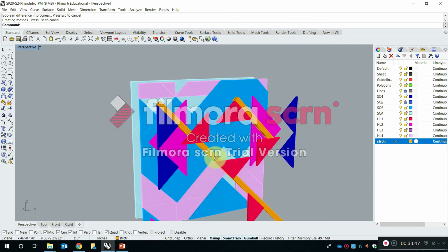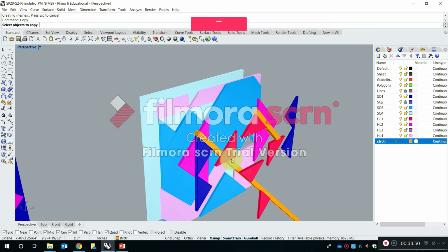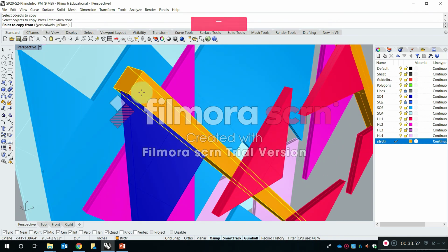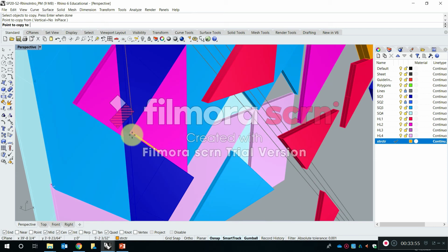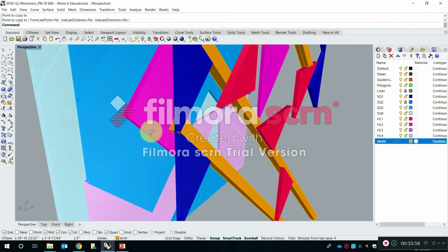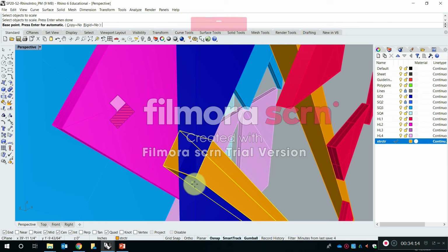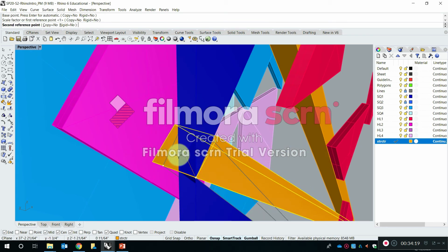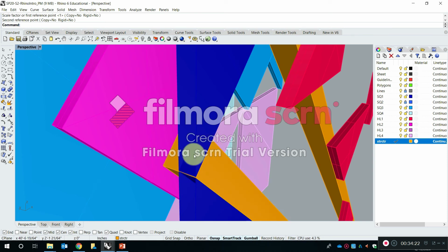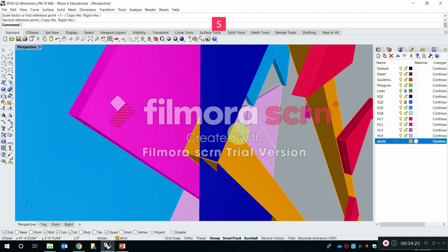All right, and let's say that once you have one of these basswood sticks, you had 1/8 inch sticks because that's what you found. But now you're planning and doing this project again. It's like, man, I really like how Javier had this basswood stick that was 1/16. Much cleaner. So I can do a scale now of two directions. Select the basswood stick, from there to there and to there. Hey, what happened? Well, let's just scale it all together.